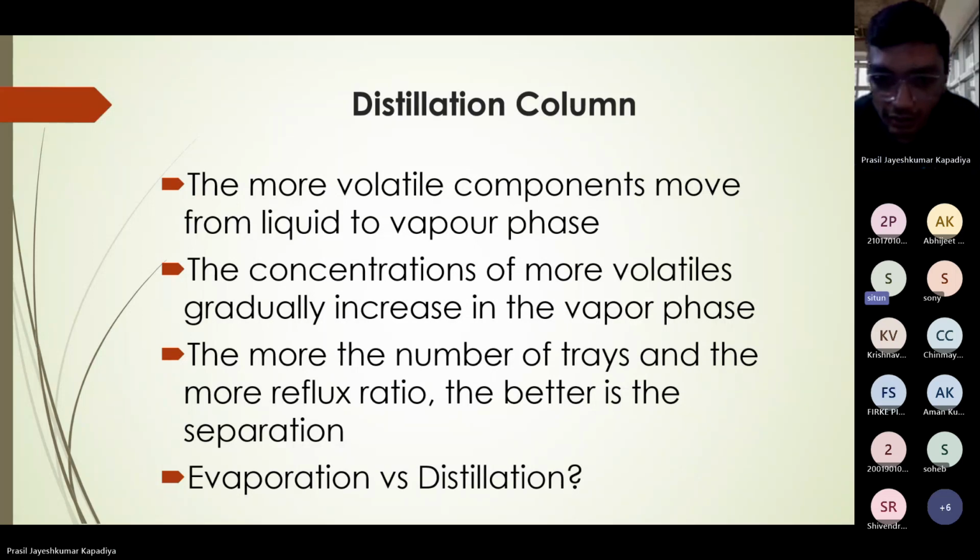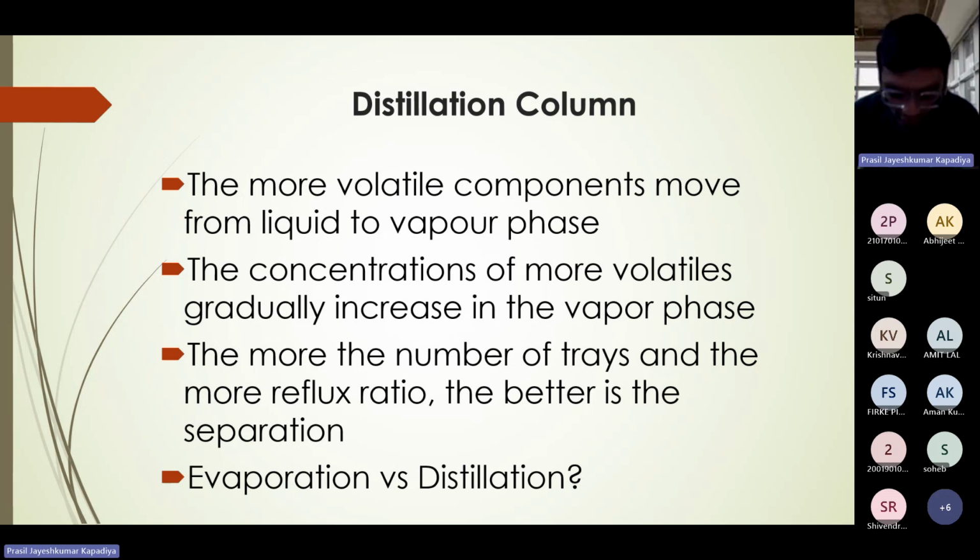Distillation is liquid-liquid, evaporation is liquid-solid. No, not exactly, that is wrong. Evaporation is used for increasing concentration, and distillation is used for separating the components. Okay, increasing concentration. So let's say feed concentration. Okay. Anyone else?